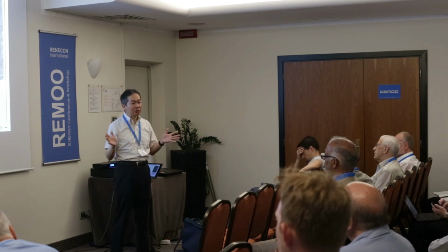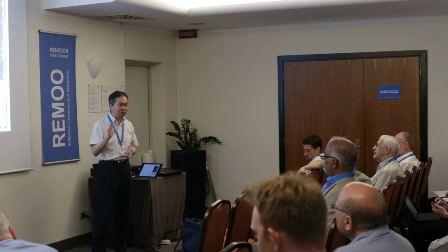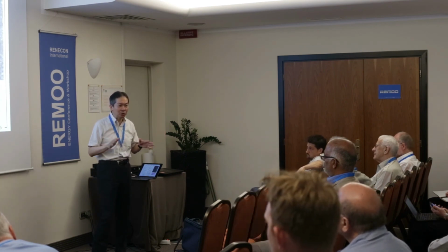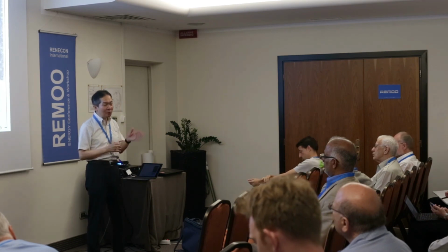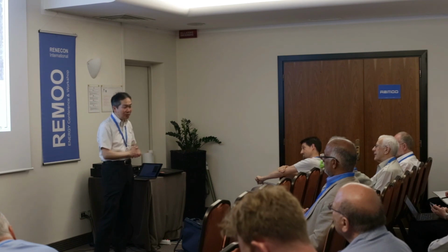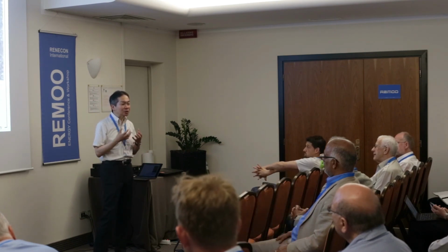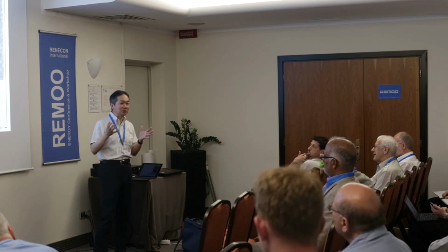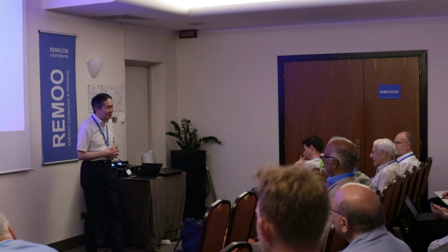Even if we change the virtual mass coefficient in the simulation, it doesn't give any big difference, so you don't have to worry too much about its value. A much more important thing is that if we neglect the virtual mass coefficient, we have lots of numerical problems because the system of equations is ill-posed, so we have to be really careful.